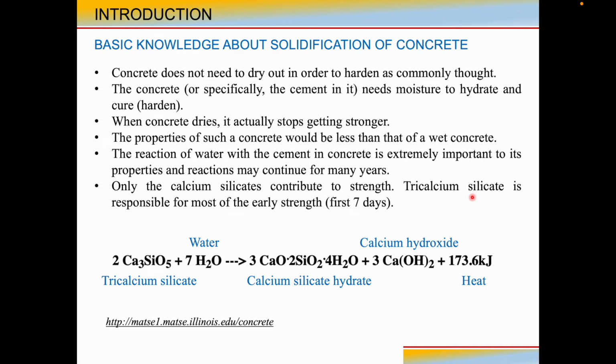The reaction of water with the cement in concrete is extremely important to its properties, and reactions may continue for many years. Only the calcium silicates contribute to strength. Tricalcium silicate is responsible for most of the early strength, for example, for 1 week.